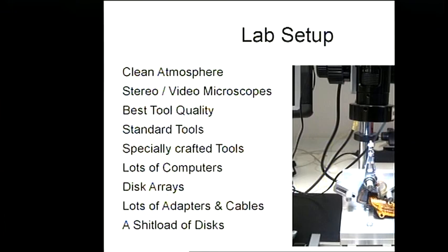What you need is a clean atmosphere. Most of the dust in our business is introduced by the customer drive itself. It is not from the surrounding air. So the first step is always to clean the media you're getting in prior to analyzing it. Because when you open a dusty cover from a hard drive, of course the dust goes into the hard drive.